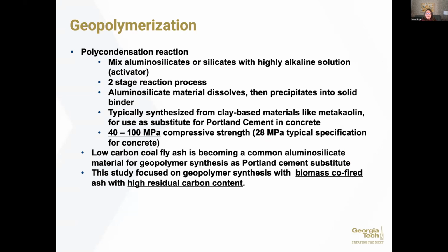So this is done these days, usually using a clay-based material like metakaolin. We can use it as a substitute for Portland cement in concrete. But what we can do is take some of these coal ashes that we're disposing, and we can use these as the source of aluminosilicate for these types of reactions.